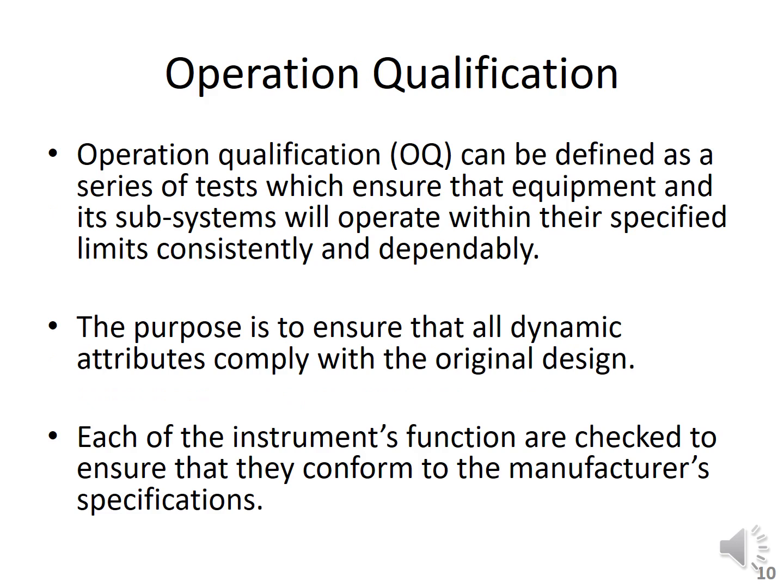The next is operational qualification. Operational qualification can be defined as a series of tests which ensure that equipment and its subsystems will operate within their specified limits consistently and dependably. Right? So you can say that the operational qualification protocol is a collection of test cases used to verify the proper functioning of a system, right? The operational qualification (OQ) test requirements are defined in the functional requirement specification.